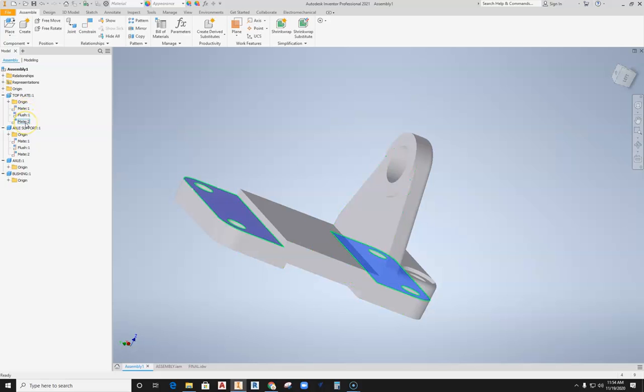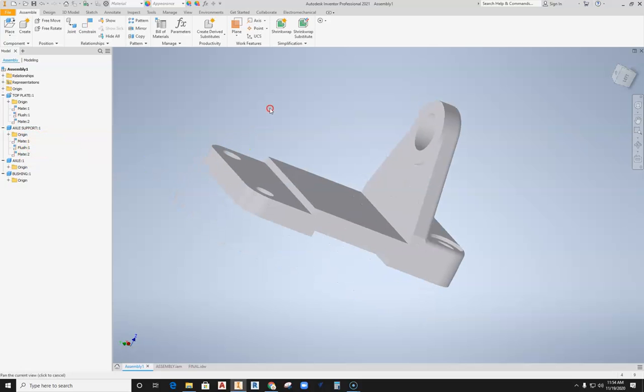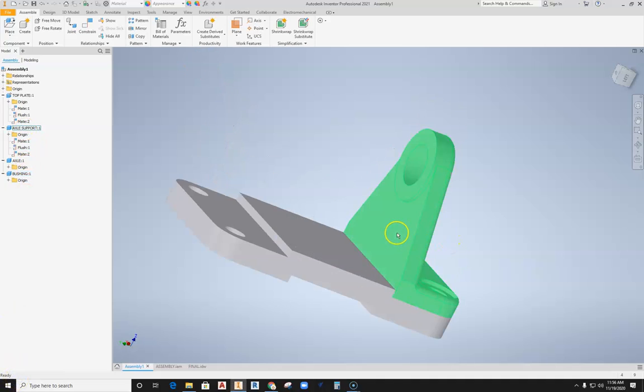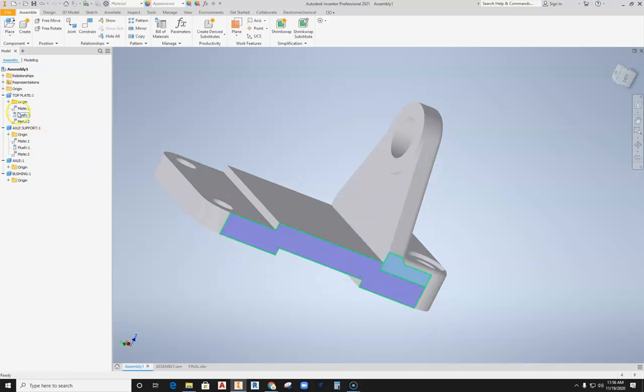And you can see a history of the constraints that are holding the part together. When you mouse over them, you can see the relationship: what was put together, and then of course flush, meaning it's a flush or a mate. And you can see how it comes together. If your model's not functioning properly, it's probably because one of these mates has not been accurately applied. This particular operation took 3 different constraints: a mate, a flush, and a mate.